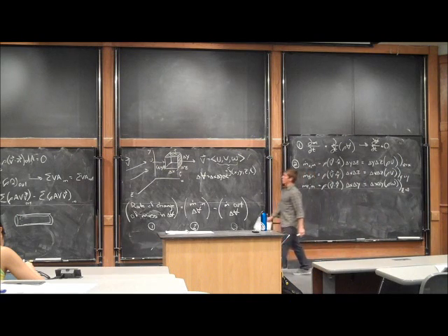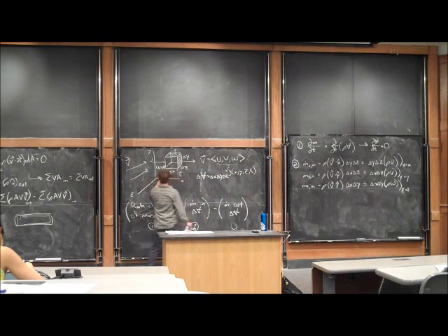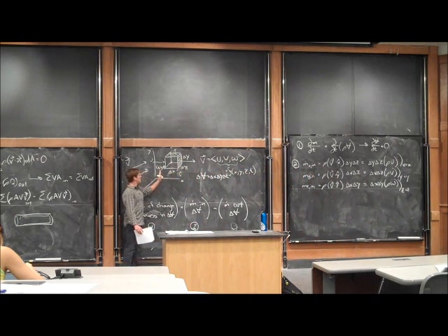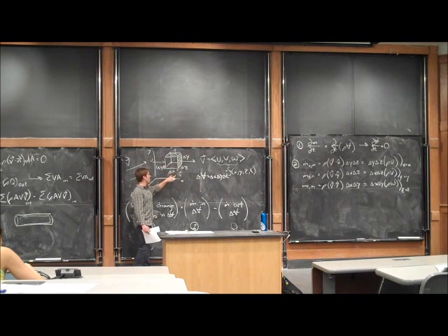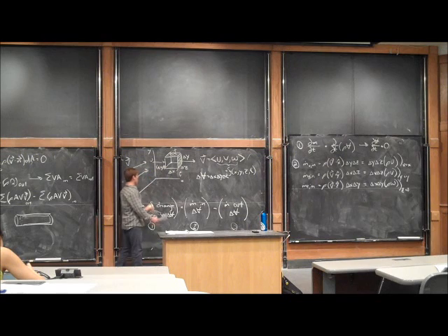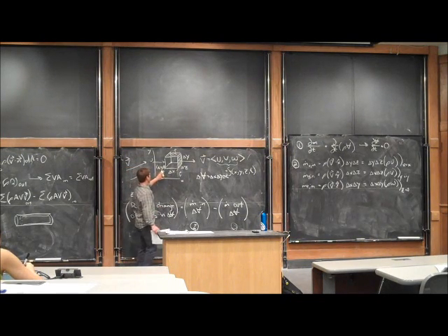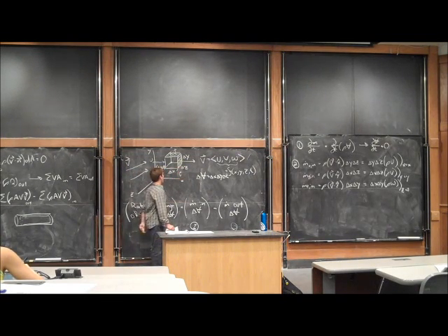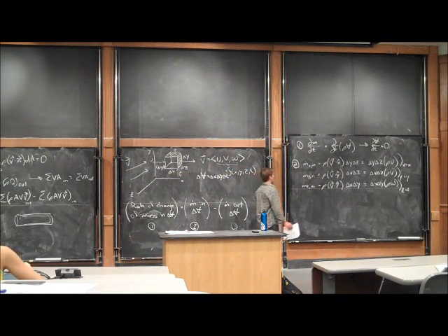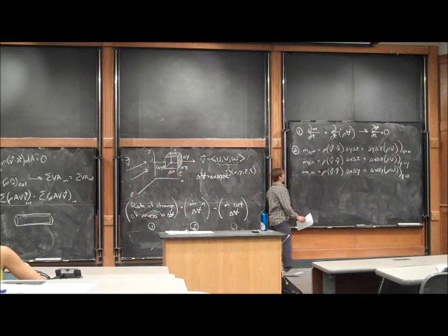However, as we step through this cube, as we move from one side to the other side, our velocity field is going to change. And so our outflow of our mass might be different due to the step delta x that we took from the x location forward. So this is a very, very large cube. The flow here at this point might be greater in the x direction than it is as we move over here. And that way we might actually have a difference in how our flow is based from one surface of the cube to the other side of the cube.